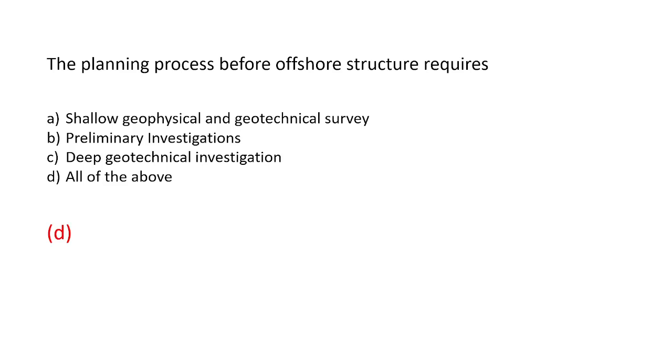If it is not a small offshore structure or pipeline but a big offshore structure, then for the whole planning we first go for preliminary investigations, then shallow geophysical and geotechnical survey if required, and then deep geotechnical investigation. So it will be all of the above.